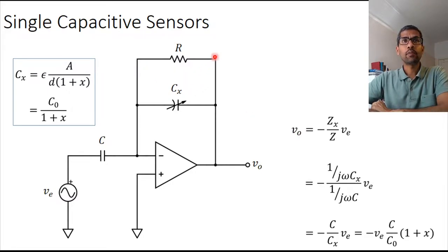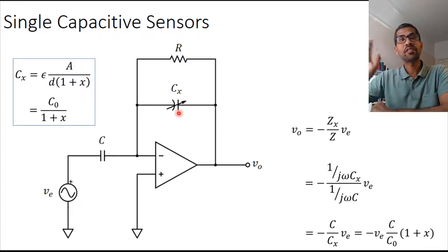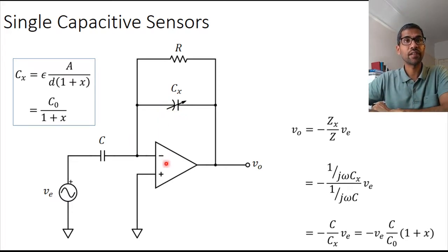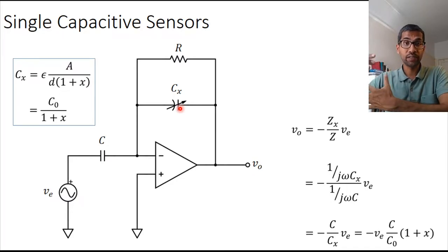Now we've not really accounted for this R in our equations, and let's just assume that this R is large enough so that we can ignore it. You need this resistance because you want to give a discharge path for this capacitance, but let's just assume that R is not really important in our circuit. Well, you may ask, why do you need a discharge path for the capacitor? One reason is because even though we assume that there is no current flowing into the input of the op amp, there is a small current flowing, as we have already looked at before. And if there is a small current flowing here, where is that current going to come from? Let's say that's a DC current. It cannot come from this capacitor because capacitors block DC voltages. So it has to come through some way, and what we are saying is it comes through this resistor.